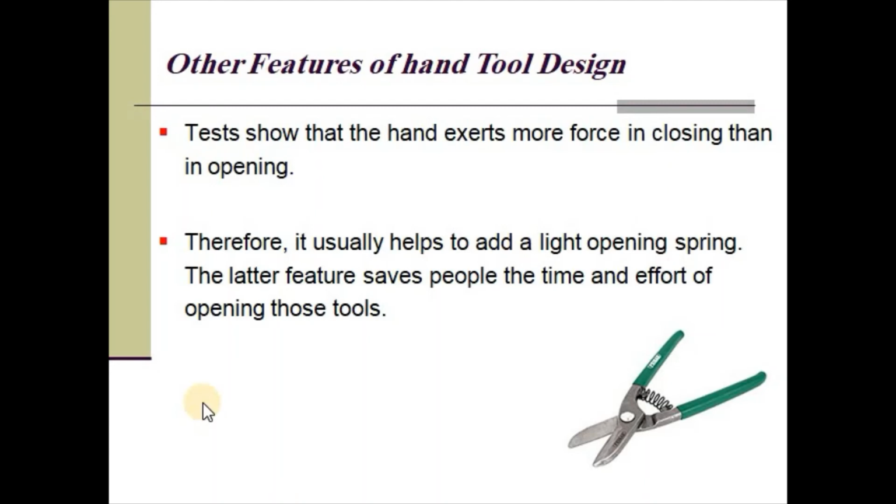Also, among the other features that are required in hand tool designs is the spring that we see in some of the tools, because tests show that hands exert more force in closing than in opening. So it's very useful to add a light opening spring because it saves time and effort of opening these tools.